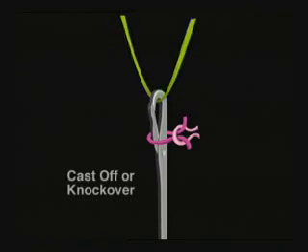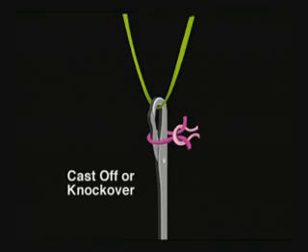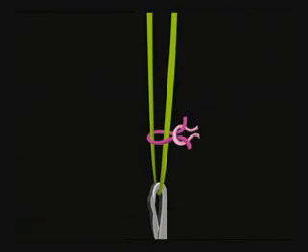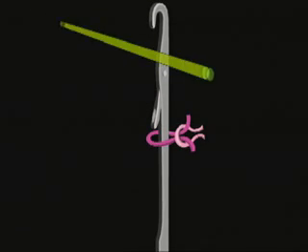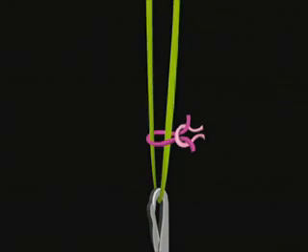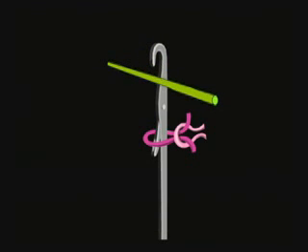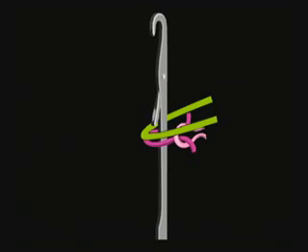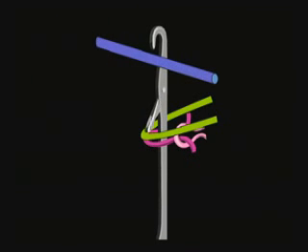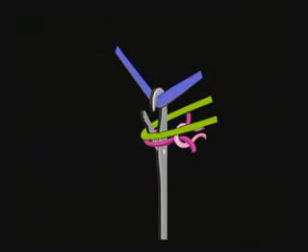A knit stitch is produced when a needle receives a new loop and knocks over the old loop that is held from a previous knitting cycle. For single jersey, this is repeated on every needle at every yarn feed. The tuck stitch is composed of a held loop and 1 or more tuck loops. Tuck loops are formed when the knitting needle receives a new yarn without casting off the old loop.